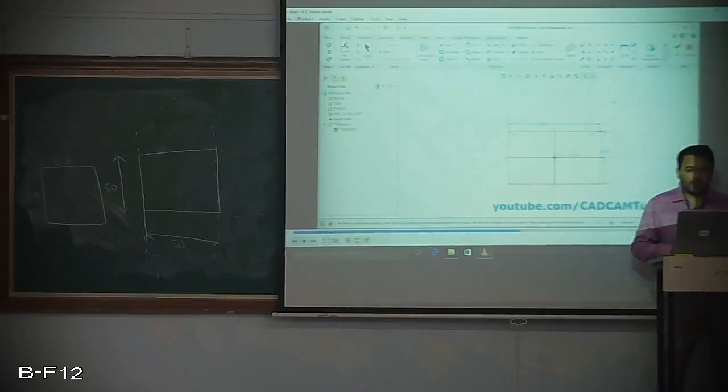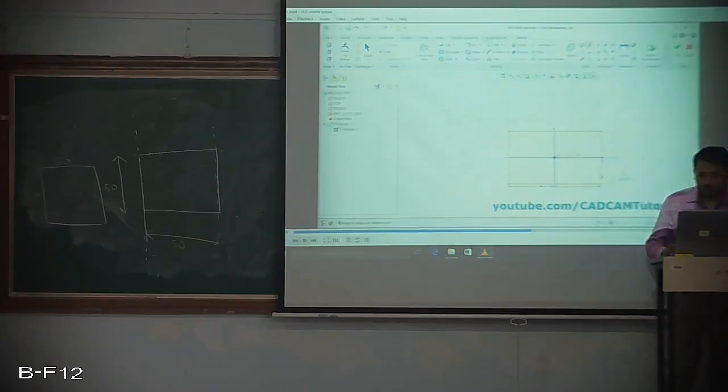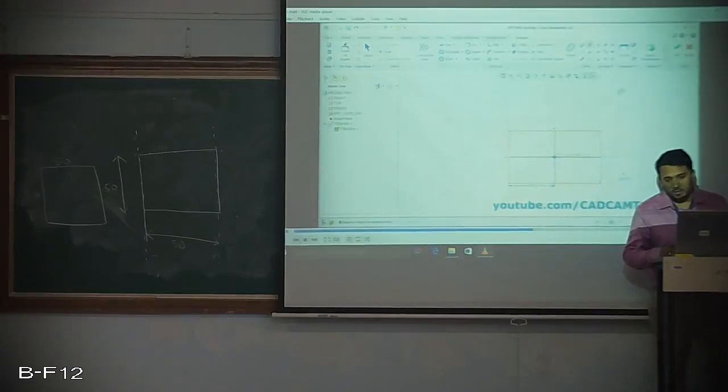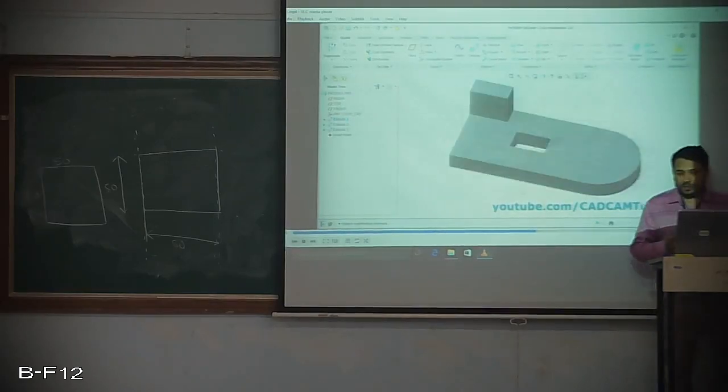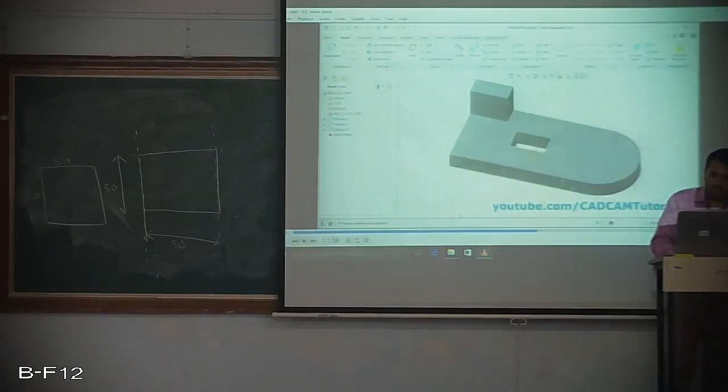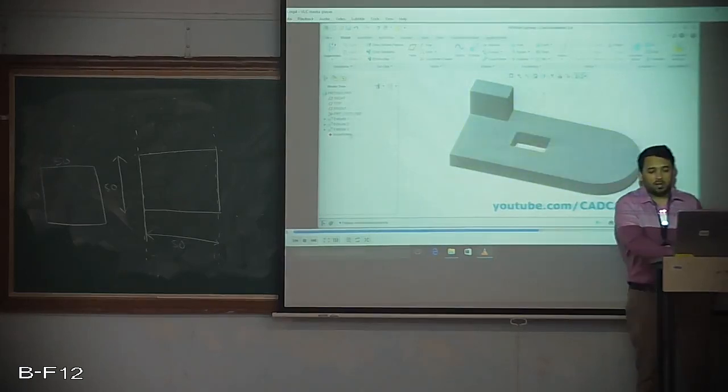So here I wanted to make a circle like shape at the extreme right corner instead of a straight edge. So I drew a circle, and again I am using delete segment to remove the excess lines. That means I am modifying the drawing. See here, the modification I have done in this sketch has been incorporated in the part also.